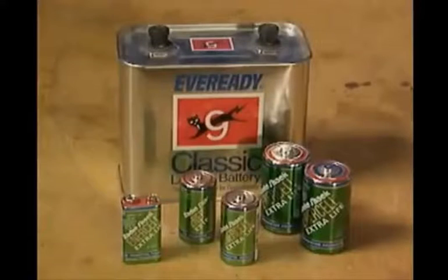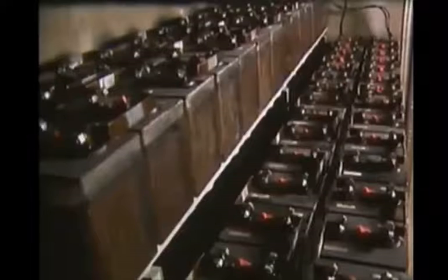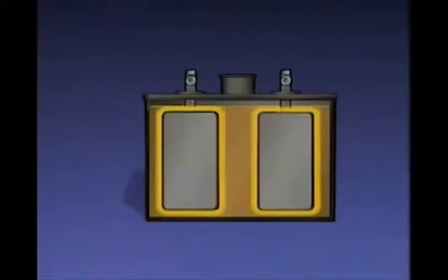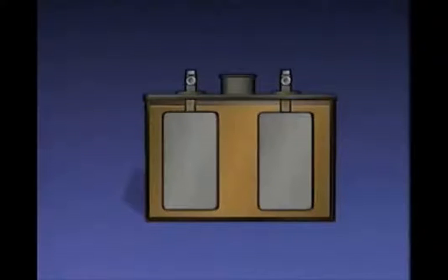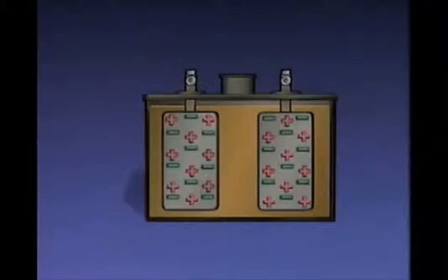Chemical action is the source of electrical potential that's at work in batteries. Whether the battery is a throwaway type or a rechargeable type, the basic elements are a set of electrodes and an electrolyte. The electrodes are generally some type of metallic material that becomes charged as a result of a chemical reaction. The electrolyte is the chemical that causes the necessary chemical reaction. Before the chemical reaction begins, both electrodes are electrically neutral. That is, they have an equal number of protons and electrons.